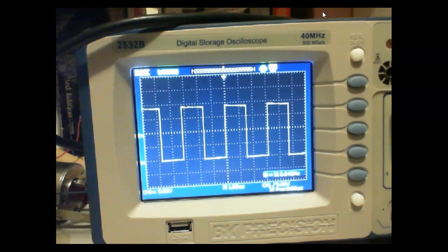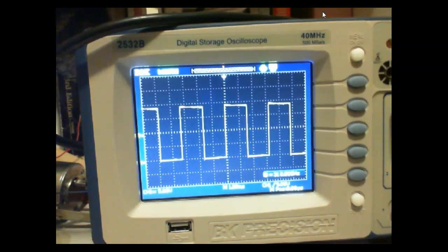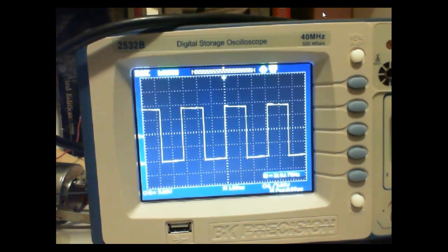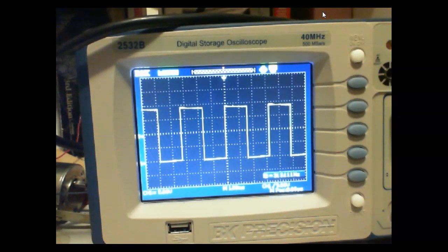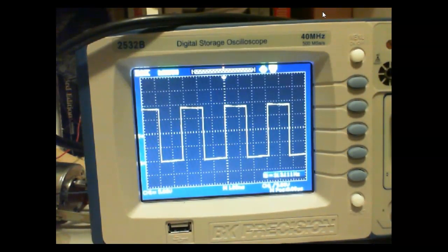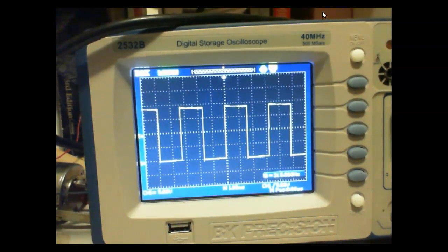What'd y'all get? Do you divide it by 60? No, because what we're doing is when I do that 1 over, my time I'm measuring in seconds, right? Even though it's milliseconds. Then I multiply it by 2,100, it's still in seconds. Then I take the reciprocal, it's going to be revolutions per second. So I got revolutions per second, and I want to convert it into revolutions per minute. So how would I take seconds and convert it to minutes? I'd multiply it by 60, right?